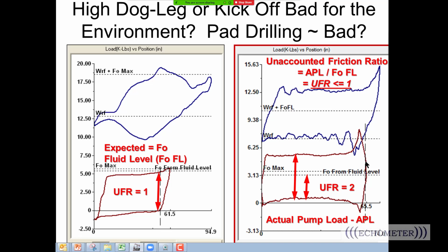When we did the Sandia data where we measured downhole forces, all those wells were vertical wells with really nice well bores, no dog legs. So this project we're working on is to try to measure mechanical friction, identify the location, and then come up with a method to calculate it. And there'll be two parts. One part is related to the dog legs, and another part is related to the drag coefficient. So that's a long answer.